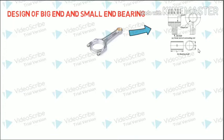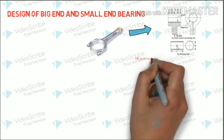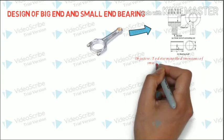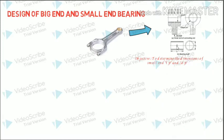All you have to find out is the diameter of the bearing and the length of this bearing. Once you have found these two, your design procedure is over. Effectively, the objective here is to determine the dimensions of the small end, which is the length LP and the diameter DP. The subscript P is used because this portion is attached to the piston pin, so to denote piston, the subscript P is used.